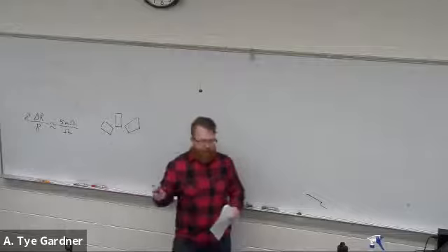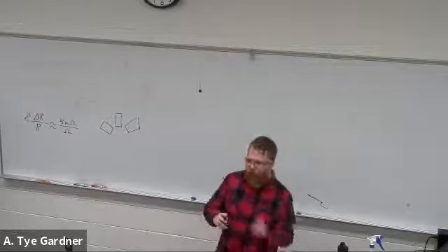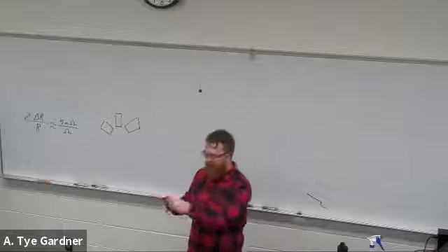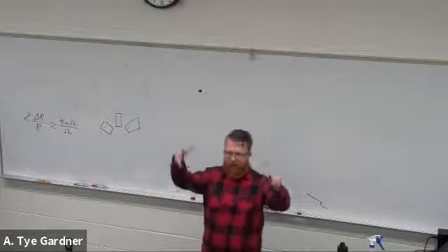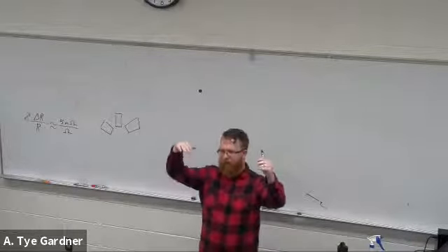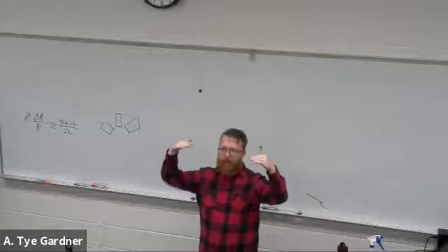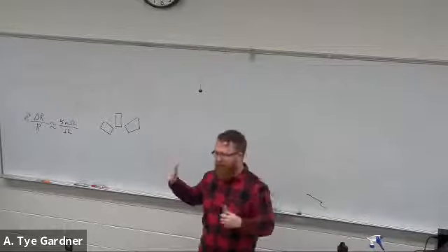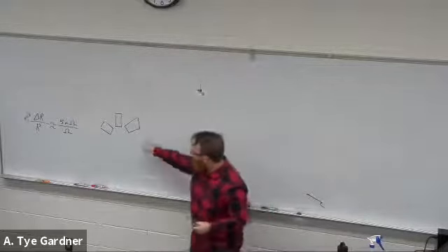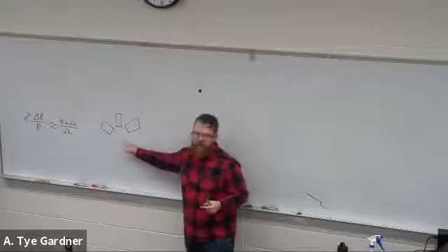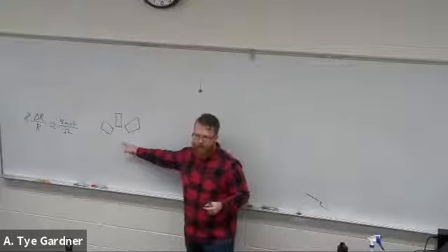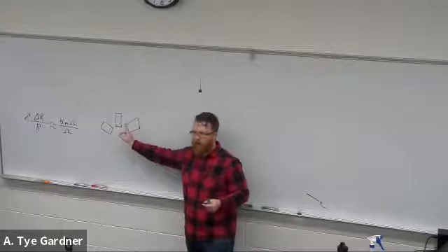Because unfortunately, if I measure strain on that guy and I were to hang a weight on it, if it wasn't perfectly balanced and it twisted at all, that is also strain, right? It doesn't differentiate between the direction of strain. So adding additional directions can give me higher accuracy in the amount of strain in the direction that I'm wanting.